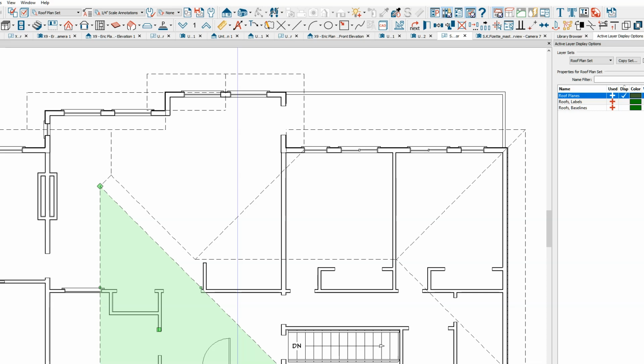The one I've got highlighted needs to move to the right, essentially. And that will make the ridge line up with this ridge right here. So to figure out where to move it to, there's a couple ways of doing it. You could just do manual roofs.